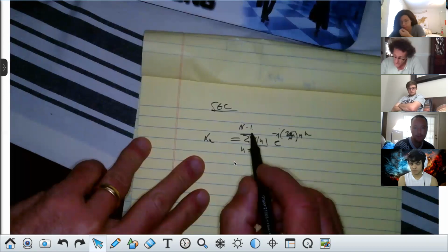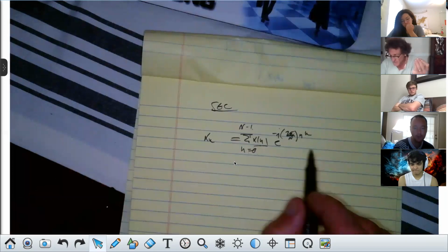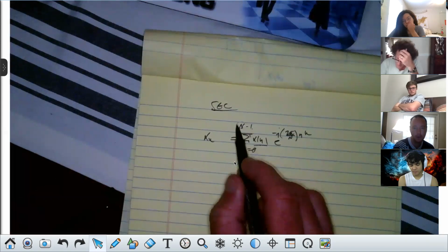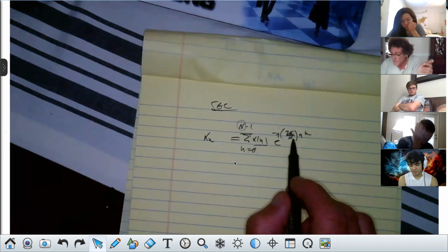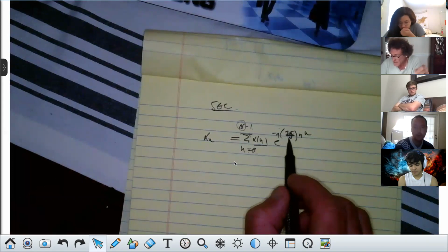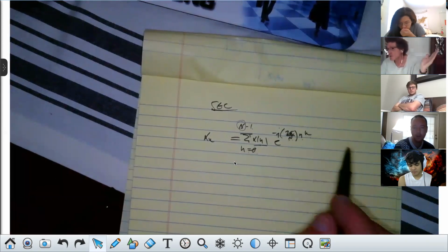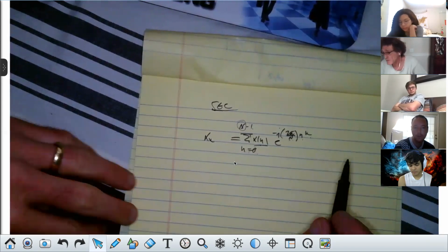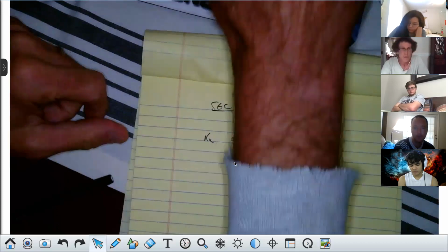Well, if you're going to do an inverse FFT, then what you have to do is have the vectors the same length. So what we actually do is make N here the same length as our output Y. And then what you can see is because of the 2 pi over N, this is going to be a much smaller number. So when you index on X, the amount of angular change is reduced. All right. You follow me on this? In fact, what you end up getting is, I'm going to shut this down and show you.